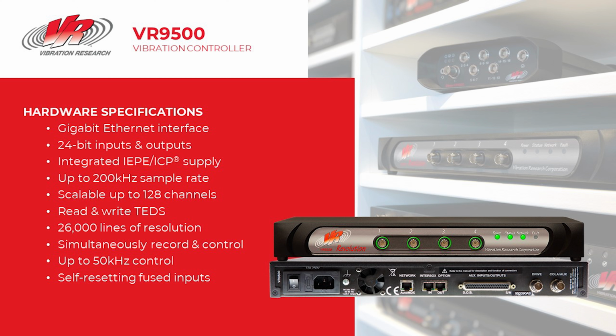Back of the 9500, there is the drive output to drive an amplifier or any shaker system really. It also has a COLA output for hooking up to a stroboscope, or sometimes you can use this in a dual phase setup for multiple shakers. Next to that are the aux inputs and outputs. Those can be used for digital and analog type signals to communicate with external equipment.